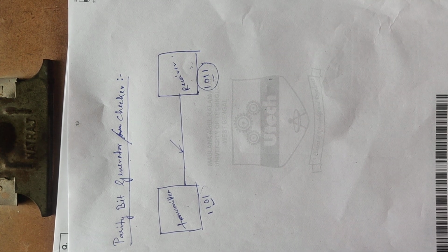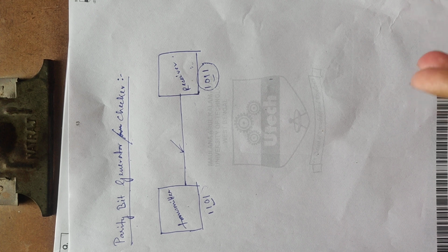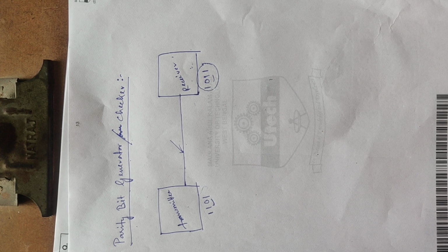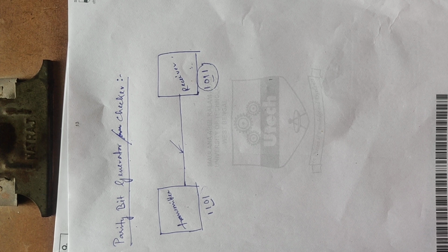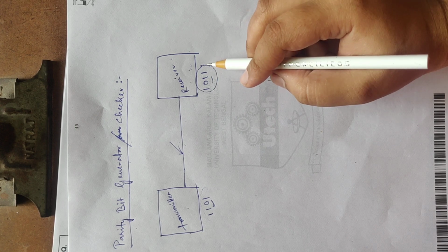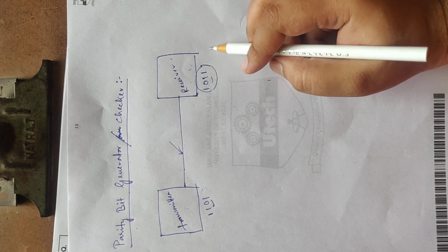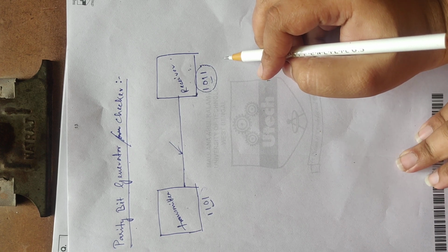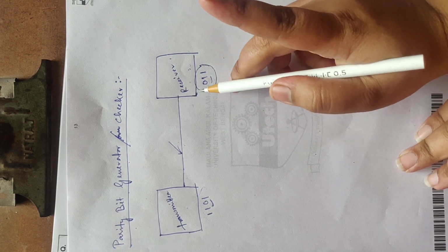Now, binary data, when transmitted and processed, is susceptible to noise that can alter its ones to zeros and zeros to ones. To detect such errors, an additional bit called a parity bit is added to the data bits, and the word containing the data bits and the parity bit is transmitted. At the receiving end, the number of ones in the word received is counted and the error, if any, is detected. This parity check, however, detects only a single error.